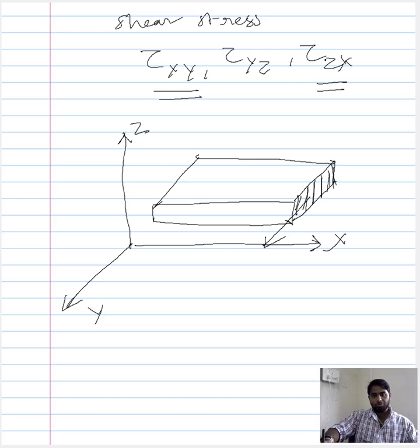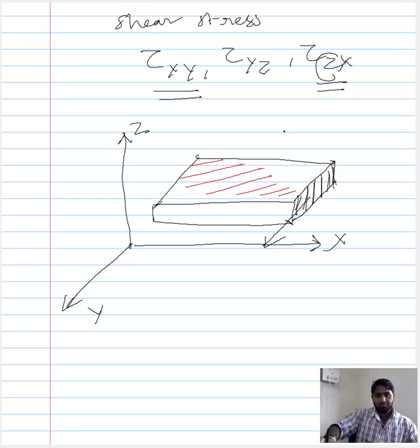Now let us talk about this shear component. From the way this shear component is described, this is associated with the z plane. The z plane is nothing but the surface of the plate, and that means the area associated with this stress is considerably higher. Since this area gets into the denominator, we can write that tau xy is very much greater than tau zx.